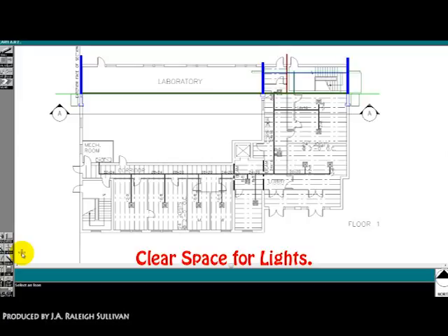You must look around at the rest of the building and decide what the minimum interstitial space has to be to accommodate the worst case scenario. Once you've done this, you can draw your joists and ducts in at the proper heights.